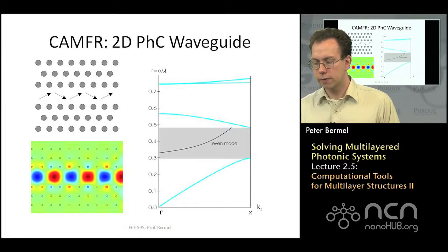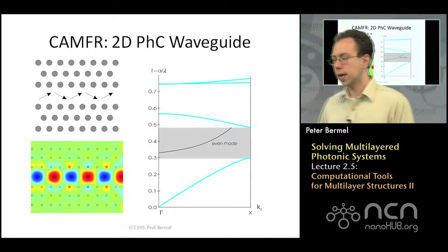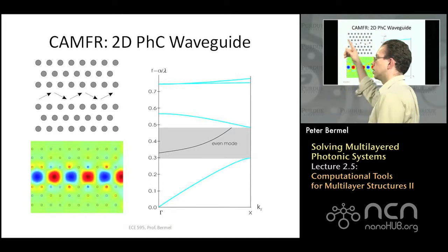So if you have a structure in which you have two triangular lattice photonic crystals that are separated by a small air gap, then that's a row of defects, or a waveguide. And so you have a 2D photonic waveguide in this case. And you can split this up so that you only have to represent effectively one period in this E direction. And you can create a slice in this direction in order to look at how strongly the light is going to be confined.